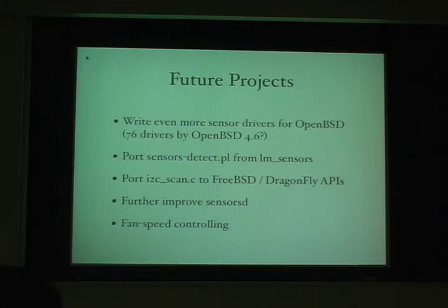So you can run the fan at, say, 40% voltage, and then 40% voltage will be around 5 volts, and it will make the system less noisy, and you can still put the voltage onto a higher value if the temperature goes up, and if the temperature goes above a certain limit.